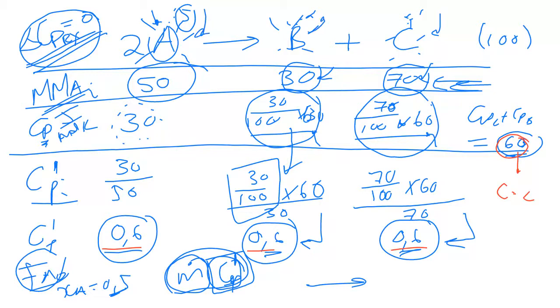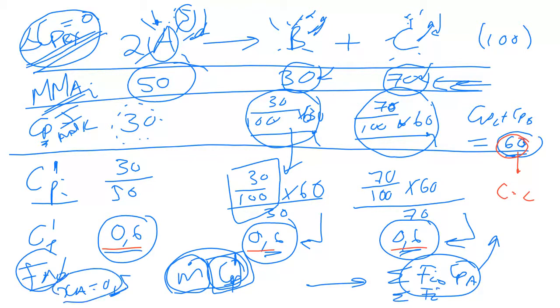How many moles of B will I form? How many moles of C will I form? And then you calculate, just taking F_i naught, which is just my A coming in, times its CP value at the inlet, and I calculate using the molar flow rates of each of my different components using my XA and their CP values that I've assigned to them.